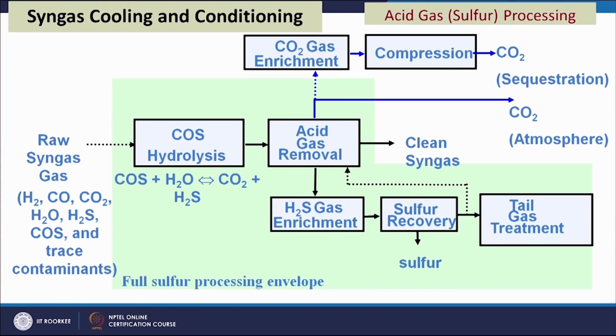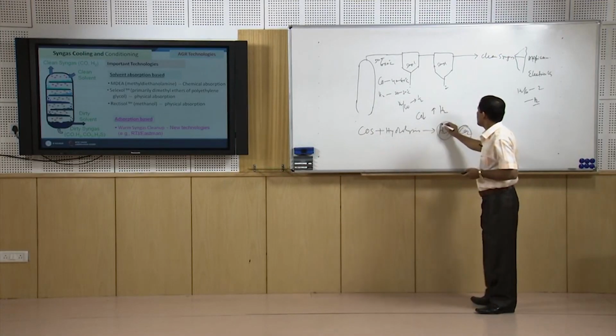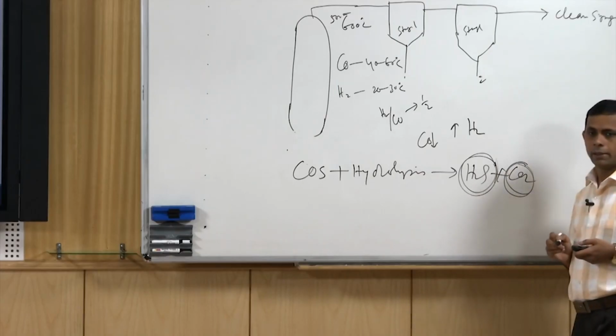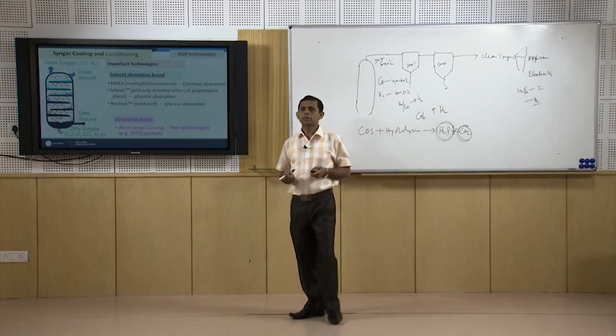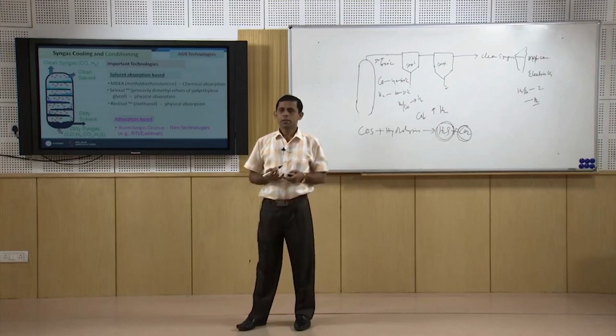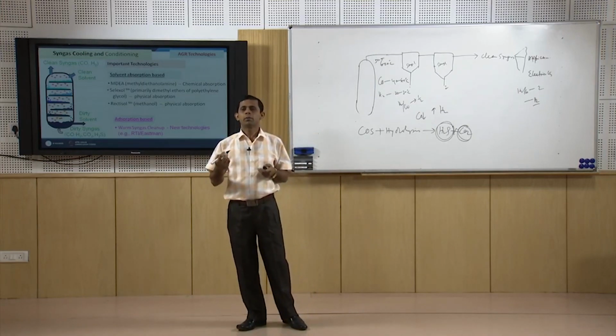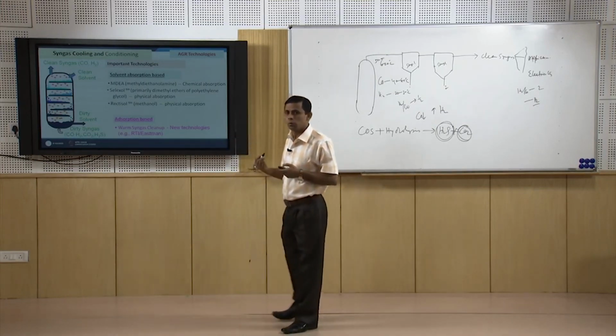So, this is the acid gas treatment process, and for the removal of H2S and CO2 there are a number of technologies available, and most of the commercial technologies are based on absorption processes, and the recent trend is to develop adsorption processes or warm gasification.